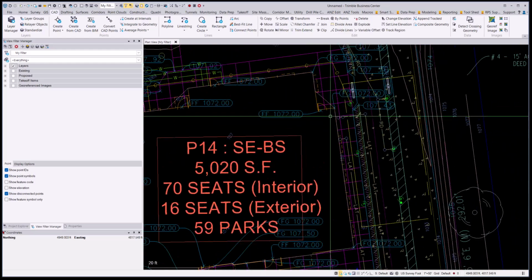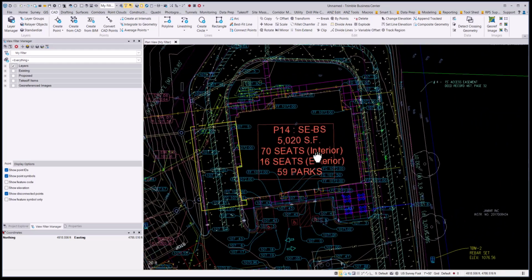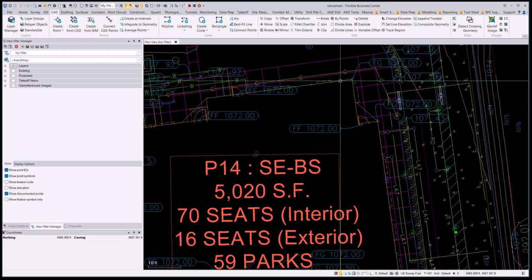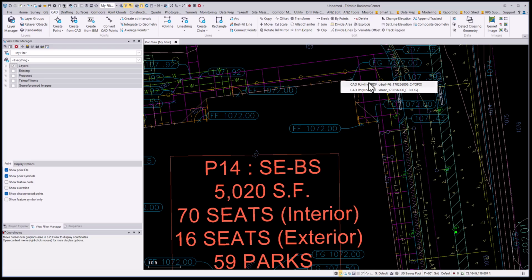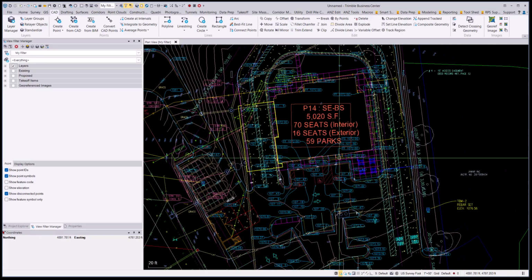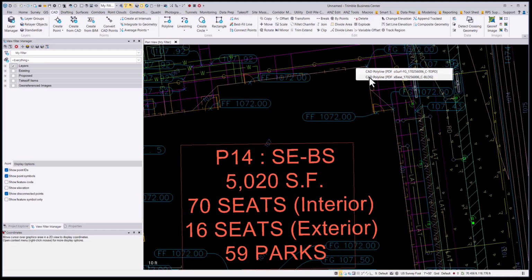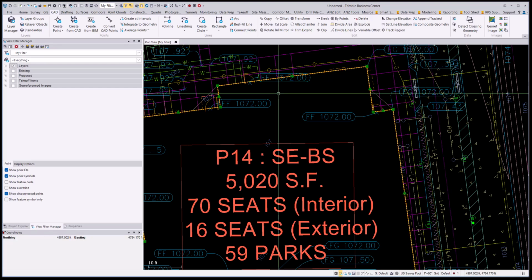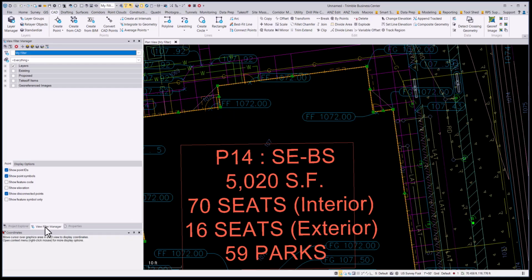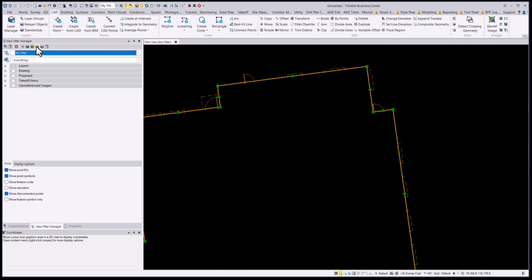So if I zoom in around the building perimeter, there usually is a boundary line. Yeah, there. So if I zoom in around the building outline here and I pick, it says there's two items here, and I want to use the C building one. So I'm going to pick it, and then I'm going to do our view filter manager, isolate objects, isolate only layers of selected objects.